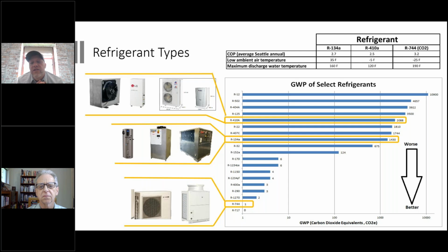And then the newer comer to the market is the CO2 transcritical cycle. It operates a little bit different than the traditional F-gas cycles. But for water heating, CO2 is an excellent refrigerant, and that's already sort of at an end game, with a natural refrigerant. So you don't have any GWP, but that's a great product. But the 134A replacement is called 513A. It just came to me.